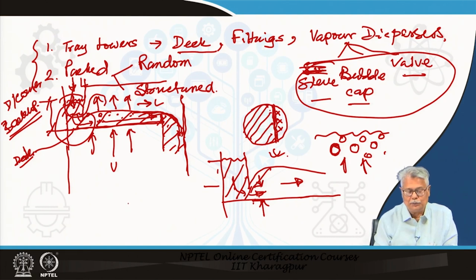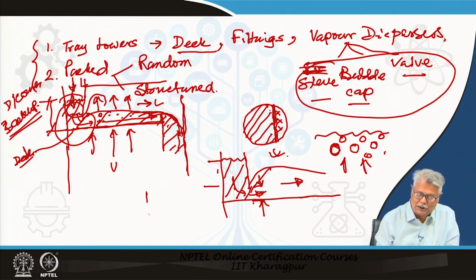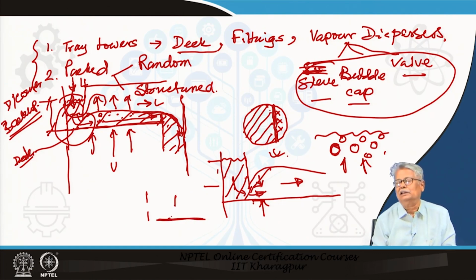So, one thing is true, that if I somehow have a very low liquid level or very low liquid flow in my column, the resistance, even with a small downcomer clearance, typically such clearances in industrial columns are never below 4 millimeters. No dimension in an industrial column should ever be below 4 millimeters, 3 to 4 millimeters usually.